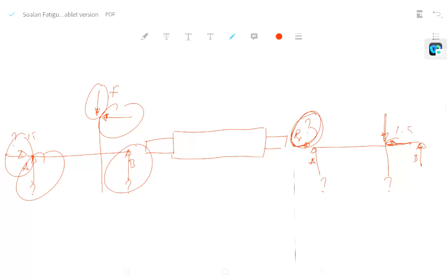After that, the same shear force diagram and moment diagram. From the shear force and moment diagram, another one you could proceed with is the torque diagram. Shear diagram, moment diagram, and torque diagram, because it has a torque. From the moment diagram, you could identify which location is the most critical one.